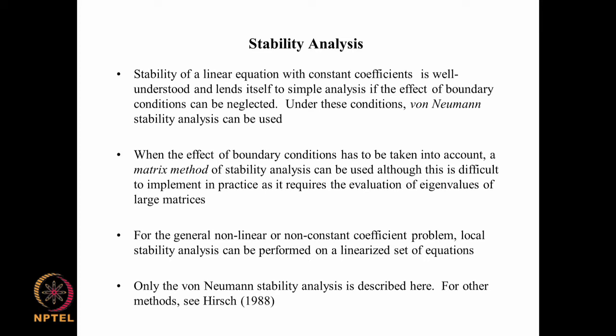if the effect of boundary conditions can be neglected. Okay. So, if the effect of boundary conditions can be neglected, and if we can treat the boundary conditions effectively as periodic boundary conditions, then we have a powerful analytical tool known as the von Neumann analysis, which can be performed on a uniform grid. And for non-uniform grids, we have more difficulty.